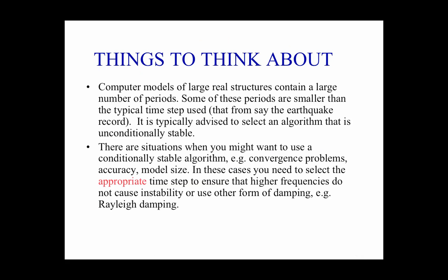Question? Hold on. Reagan. You mentioned that the stability criteria apply only for elastic structures. Yes. But then, say for instance you have a SDOF nonlinear structure, and at the most the period will elongate post yielding. So if the criterion is satisfied in the elastic range, isn't it automatically satisfied for nonlinear as well? No, it goes the wrong way on us. Because we're getting the higher frequencies start having an impact.